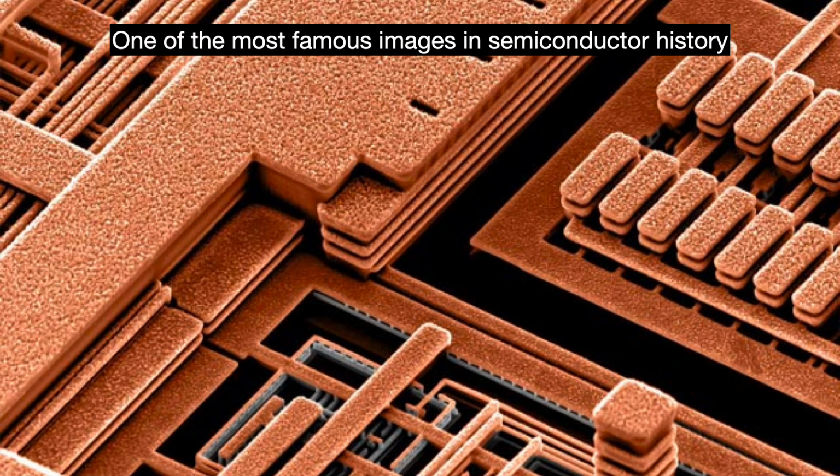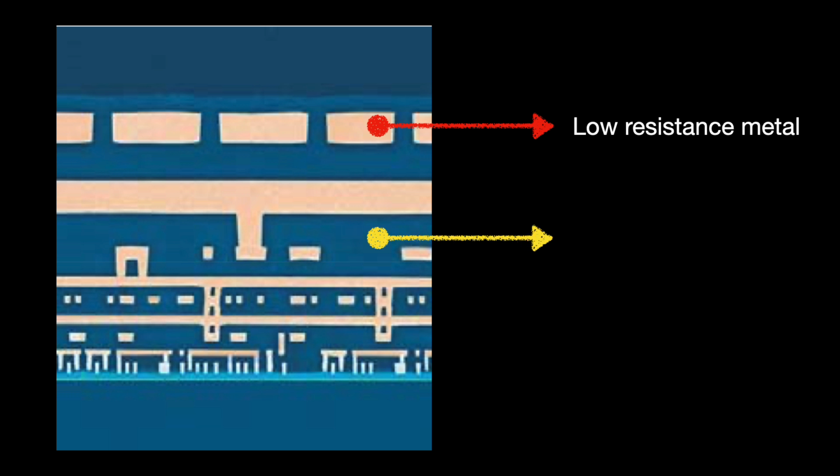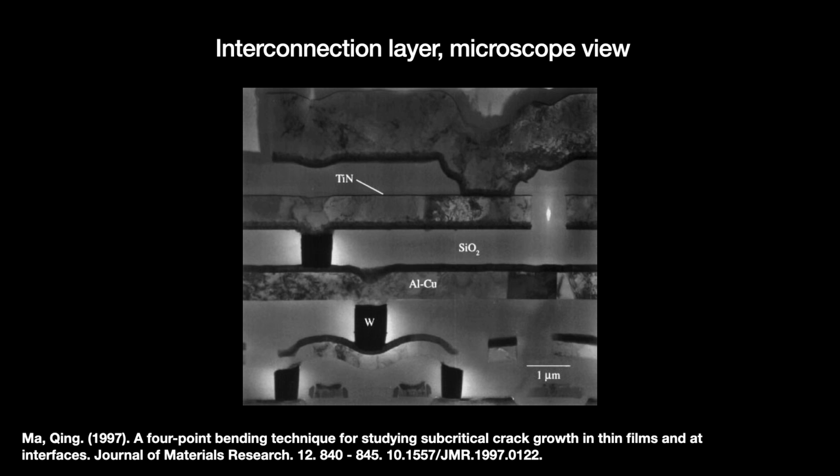The first thing I thought about when I thought about superconductors for chips were interconnects. In an integrated circuit, interconnects are wires for transmitting the electrical signals between the transistors and other circuit elements. These interconnects are usually, but not always, made from low-resistance metal, so we call them metal layers. The wires are surrounded by dielectric material, intermetal dielectric layers, that serve as insulators. For a long time, we used trusty silicon dioxide for this. These layers sit all jumbled about on top of the silicon transistors, like how strata look like in geology.